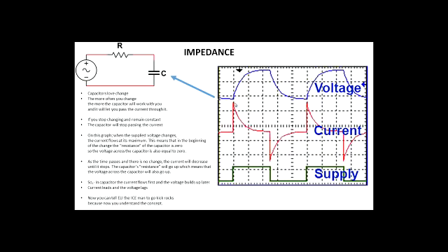The current goes high right in the beginning. Now as the capacitor charges, the current decreases, and if you don't change anything, the current is eventually going to stop flowing. So of course, when the current starts flowing at its maximum, it's almost like a dead short to the circuit. So the voltage across the capacitor is going to be zero because it is a maximum current. The capacitor acts just like a short wire. And as it charges, the voltage builds up on the capacitor. And then as soon as the voltage builds up to the maximum, the current stops flowing. See that?